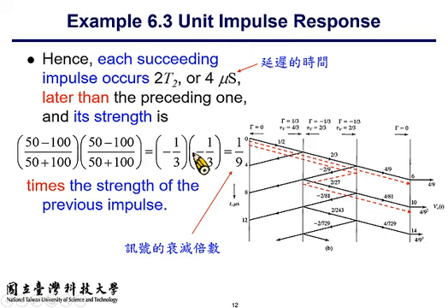of merit of the bouncing diagram is that it helps you understand what's going on within the transmission line. If you have an impulse source, like in this example, the signal will generate transmission and reflection at the interface.